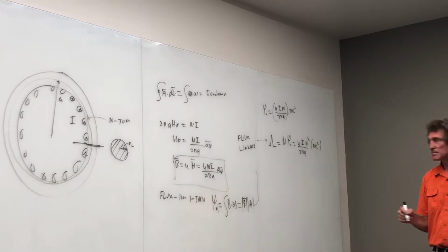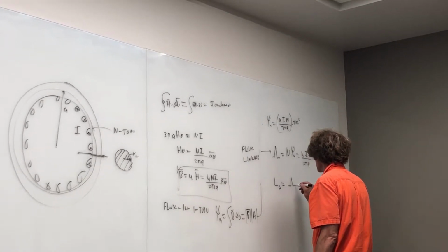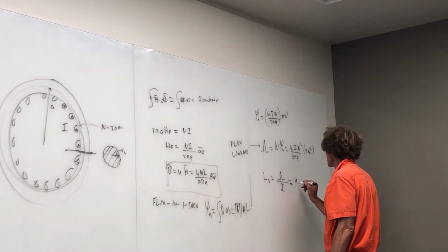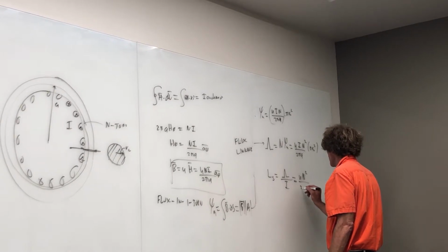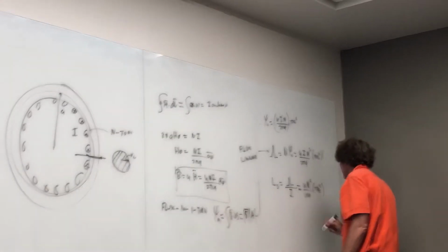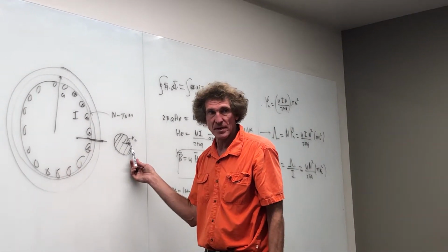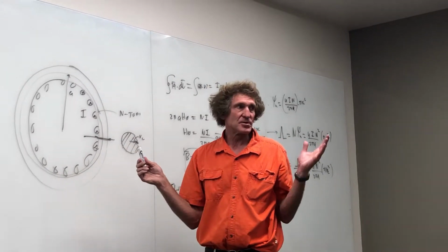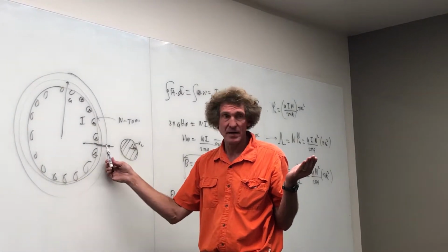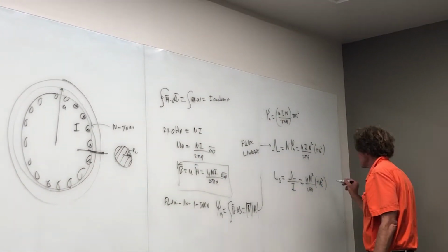And now we can get the inductance. Now we can simply get the inductance L, and this would be a self-inductance, equal to the flux linking all those turns divided by the current causing them. And that means it's simply equal to mu N squared over 2 pi A times pi RC squared. And the critical thing here is just knowing the area, the perpendicular area here. Because if this was elliptical, it really wouldn't change things as long as the largest radius of the ellipse was still much, much less than the radius A out here. It won't matter, but you have to know the area. And that's generally the inductance of a toroid.